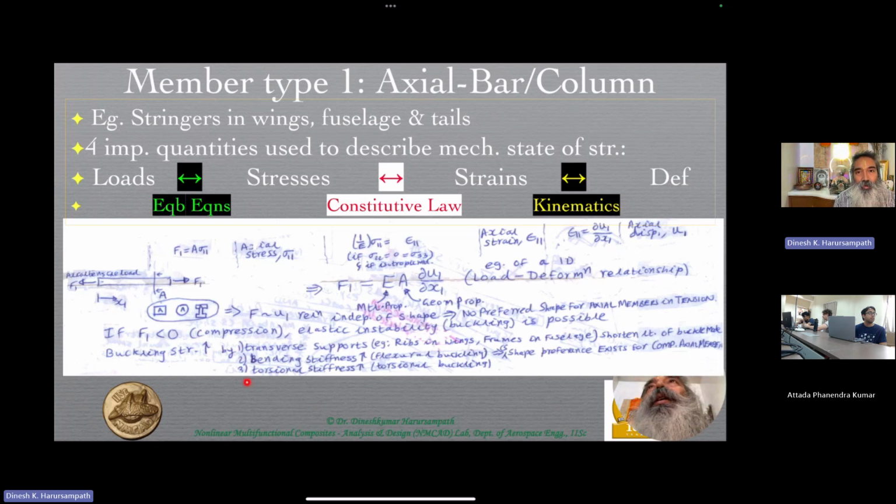So the simplest buckling formula, which you may have encountered, is pi squared EI by L squared. It depends, of course, also on the boundary condition, so depending on that, there will be a constant multiplying this expression. But essentially, it's proportional to the bending stiffness, EI, and it is inversely proportional to the length of the structure itself. And that is, of course, the first buckling mode, that is the buckling load.